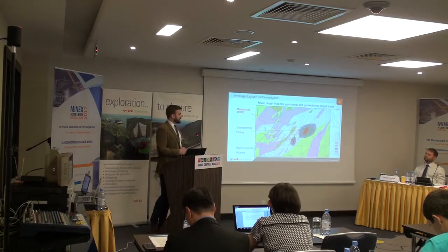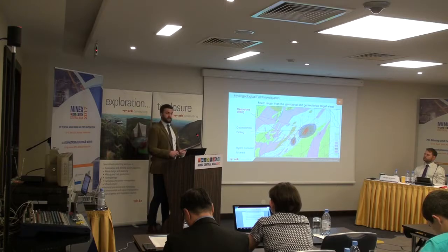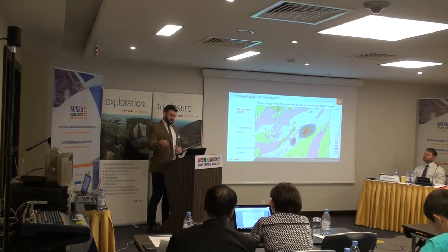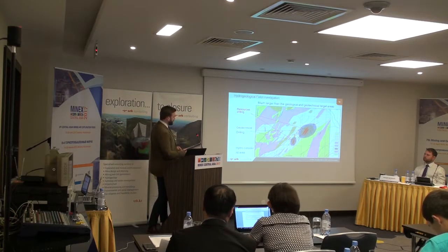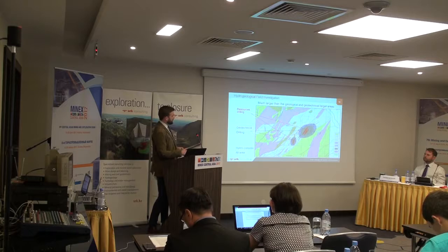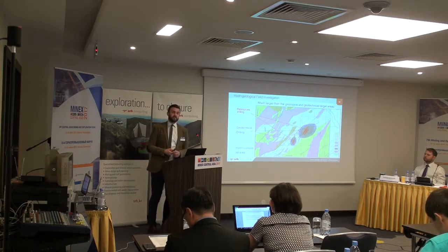I've got this slide in here which just shows, as we said, the resource drilling may just target the mineralisation shown here in red. The geotechnical drilling needs to be slightly deeper and target the waste for the pit slope design. But the hydrogeological field investigation needs to consider the area outside the pit, because that all feeds into how you develop your hydrogeological modelling.